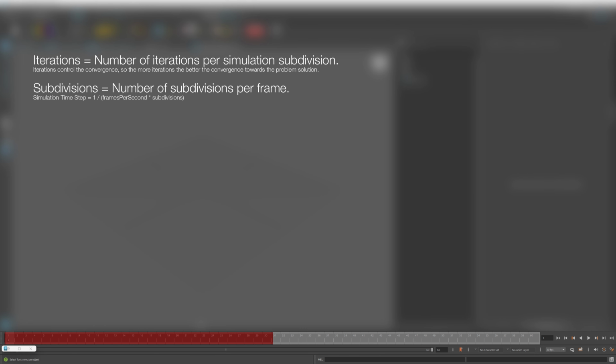Let's summarize again. Iterations is the number of iterations per simulation subdivision. Iterations control the convergence, so the more iterations, the better the convergence towards the problem. Subdivisions are the number of subdivisions per frame. So a simulation time step, which means the time step of the internal Carbon solver, is 1 over frames per second times subdivisions. So if we have 30 FPS in our timeline and 20 subdivisions, that makes it 1 over 600, so our simulation is 600 Hertz.